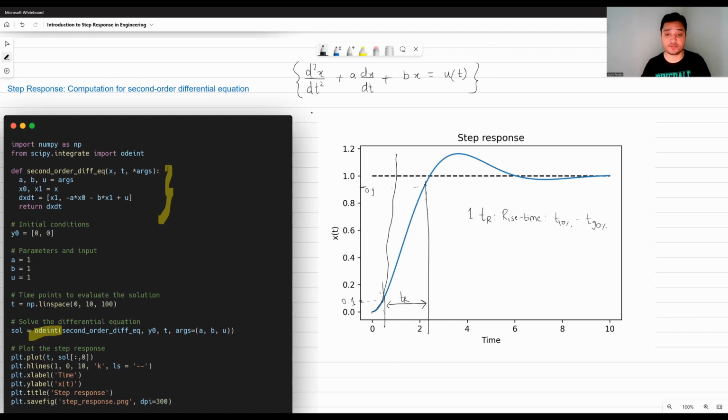But there are trade-offs to this, because what may happen is that it may overshoot because it's going that fast to the desired level. It may overshoot and be something like that. And so that's the next metric, overshoot. For the blue curve, you see that the overshoot is less than the black one.